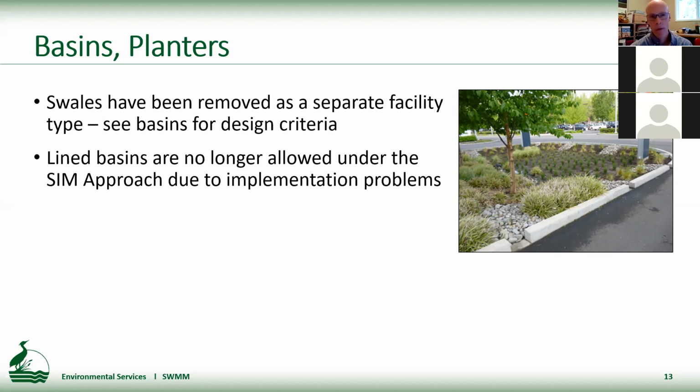Grassy swales, of course, still live on. They exist there in the latter half of the manual, but we realized there was way too much confusion about the very similar cross sections between swales and basins in the past, and we think just to stem the confusion, we've made bioretention swales part of the basin design criteria.